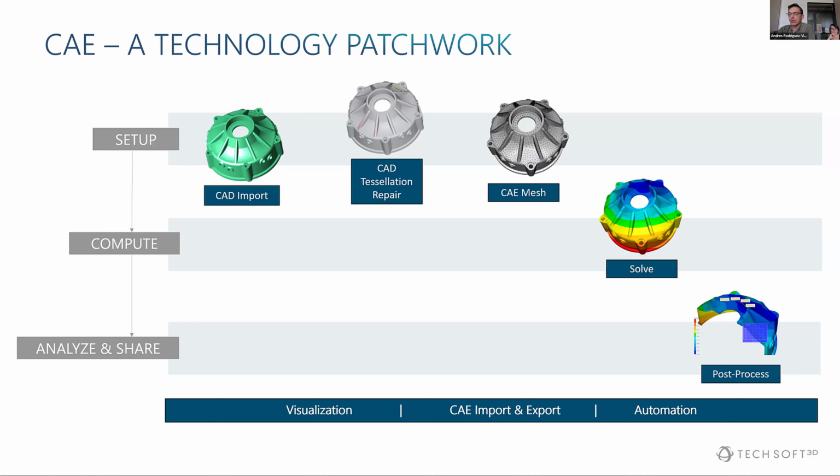A mesher imposes some constraints on a tessellation for it to work. It's a pretty well-defined mathematical object. So tessellations should not have any self-intersections, should be watertight, and strictly speaking, should be manifold.